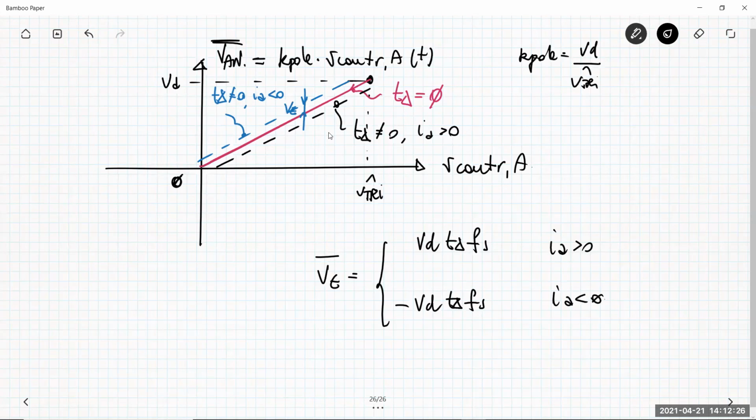This error increases with the frequency and increases with T delta. So when you are designing your own switching power pole and you have to choose T delta, be sure to take the minimum T delta that makes it possible to avoid cross conduction of TA plus and TA minus without exaggerating too much. Because you can also have stability problems if you exaggerate too much. The feedback cannot compensate the error.